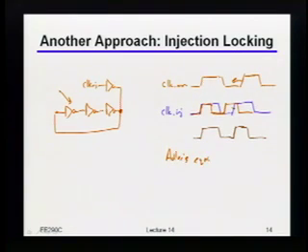Okay, that just has to do with what happens when you have an injection locking oscillator: what is the phase shift you end up with as a function of the frequency offset. By the way, another way of seeing this is like saying we're taking that ramp input and feeding it into a first order feedback loop, right? So the sharper that ramp, the more delta in phase you're going to get. And it turns out that if you adjust the frequency in either direction, meaning if you either increase the nominal frequency compared to the injection frequency, or decrease it compared to the injection frequency, you can move the phase both positive and negative.